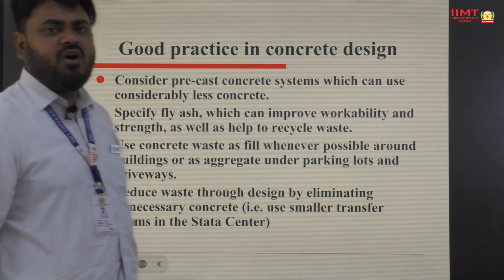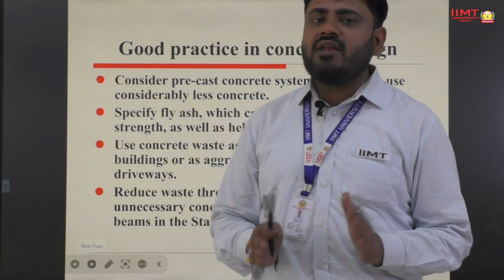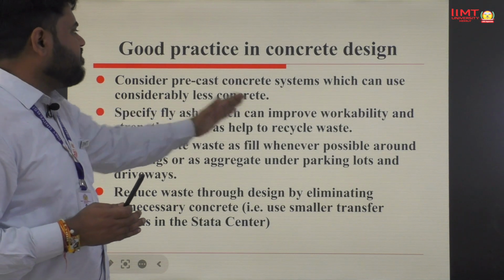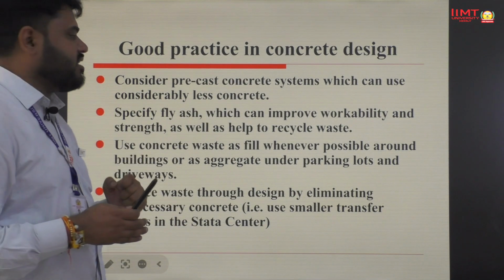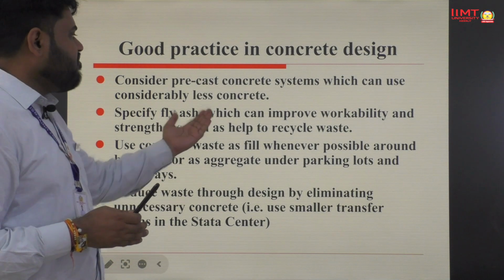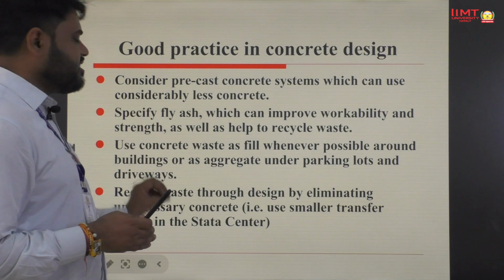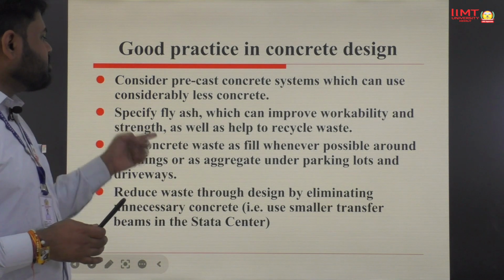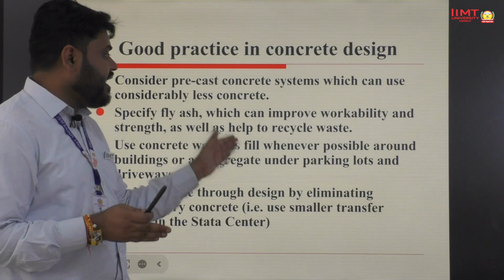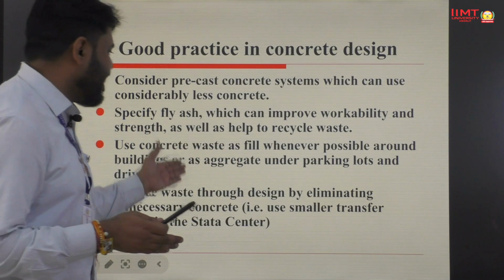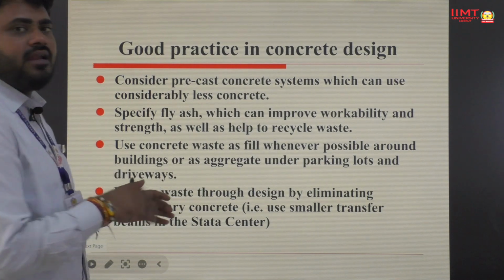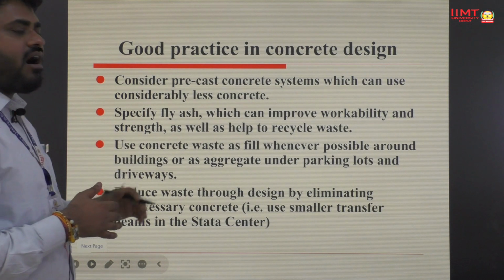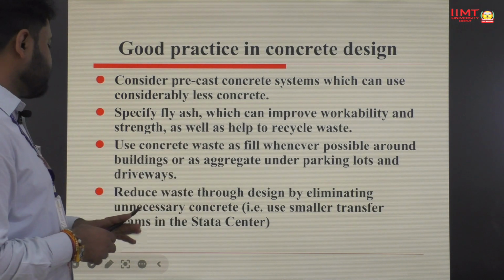Good practice in concrete. What kind of practices is required while we are going to design the concrete? Consider the precast concrete system, which can use considerably less concrete. Specify the fly ash, which can improve the workability and strength, and helps to recycle the waste. Next, use the concrete waste as fill whenever possible around the buildings or as aggregate under the parking lots and driveways. Reduce the waste through design by eliminating unnecessary concrete, like using the smaller transfer beam.